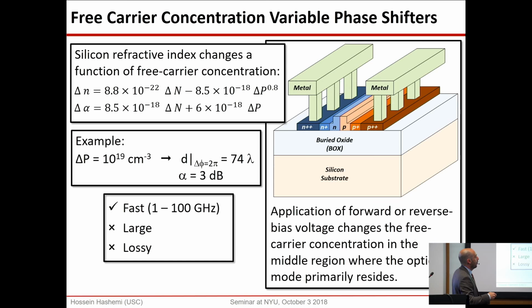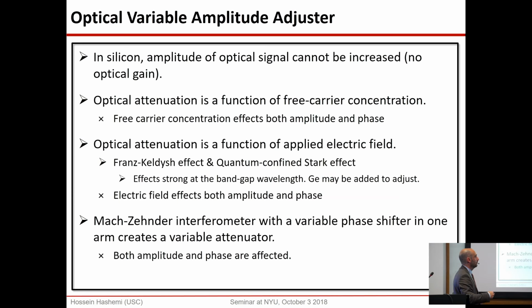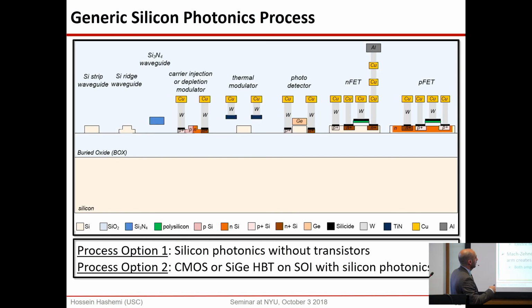Cool idea. Or I can get my waveguide and put a PN diode around it, inject carriers into it, electrons or holes. That will also create an index change. So these two can be used, and other effects. I'll get to this a bit later. Now, this one partially responds to the previous question.